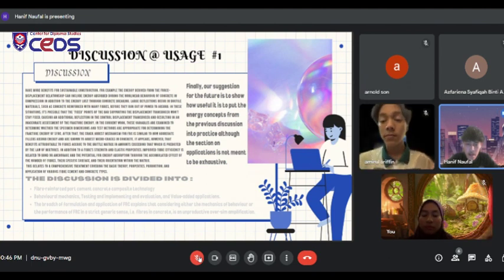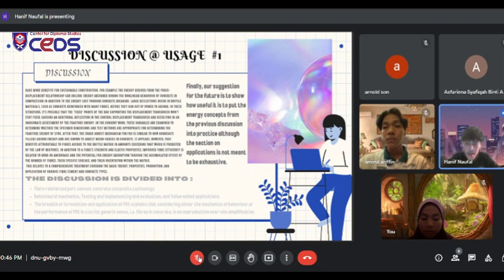After that, the crack arrest mechanism for FRC is similar to how aggregate failure absorbs energy and is known as micro cracks in a concrete. It appears, however, that the benefit attributable to fiber occurs in the brittle matrix in amounts exceeding that which is predicted by the law of mixtures.